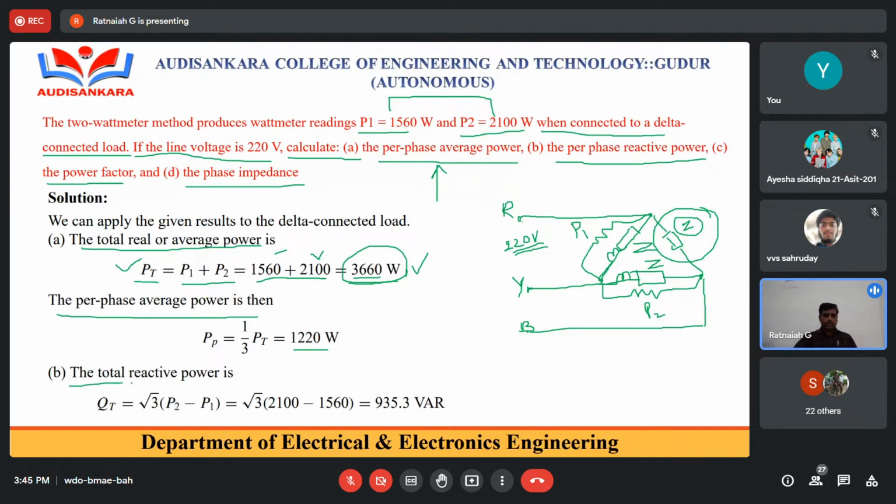Then what is the total reactive power? Remember, while calculating per phase power, that means average power or reactive power, first you need to calculate the total power. Then you can divide by 3, and only then you get the per phase power. So what is the total reactive power? The total reactive power is Qt equal to root 3 times the difference of both the wattmeters. It depends upon the connection of the wattmeters, so we have to take only the difference, not simply P1 minus P2 or P2 minus P1.